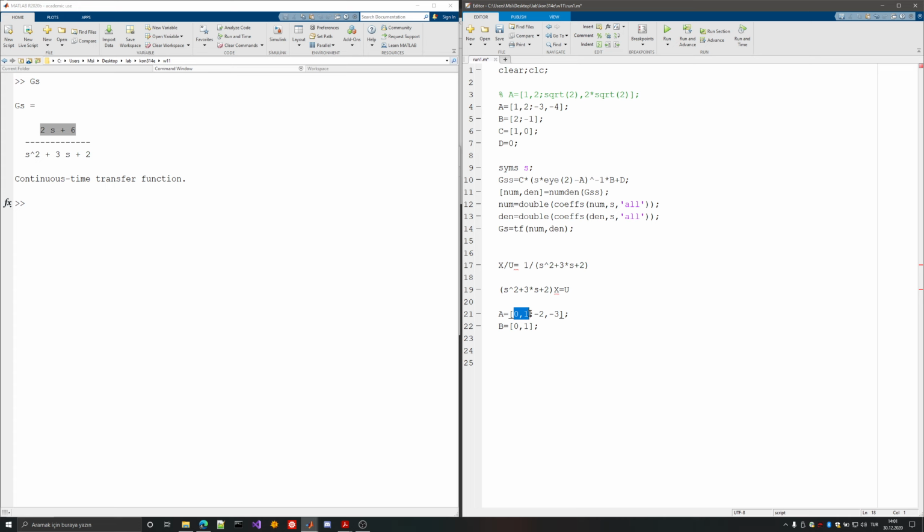That's the reason why we will have a template here, 0, 1. And then my input will be in the last equation, because all the n-1 rows are relations between the internal states. So the only state that will be used for the actual differential equation is the last state, the nth state.